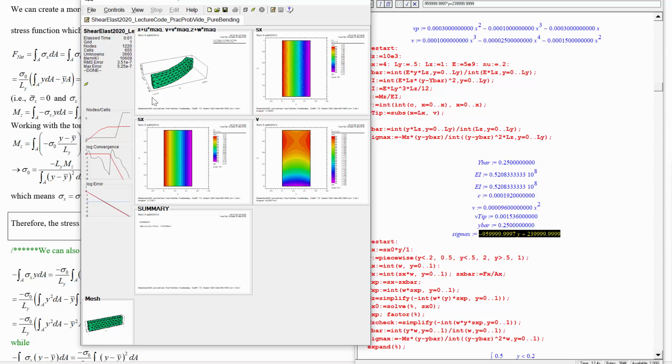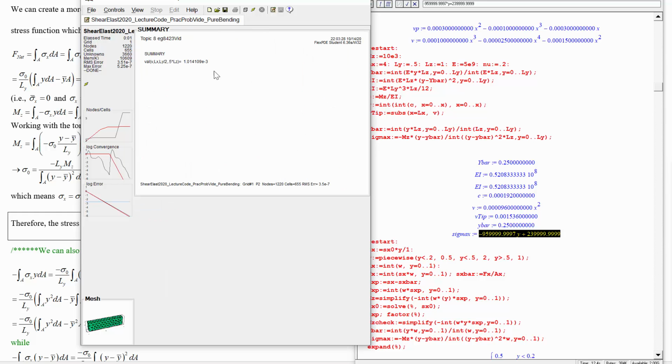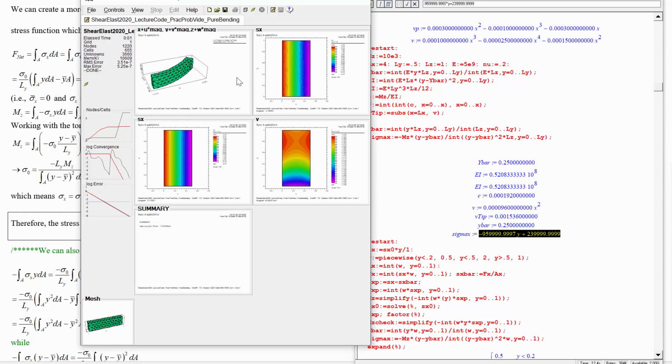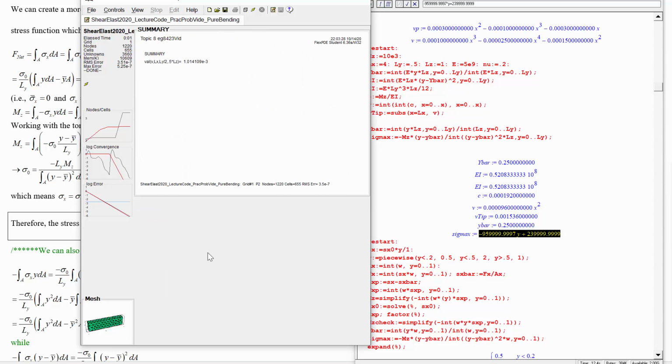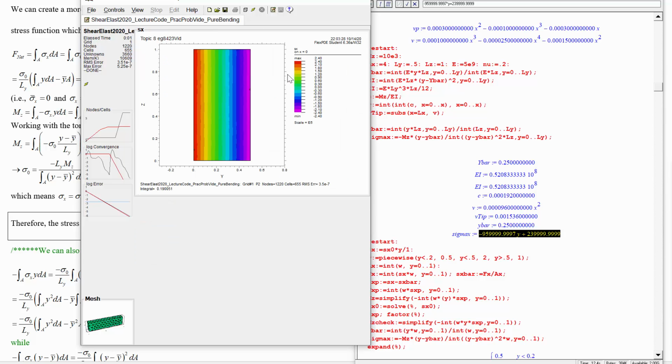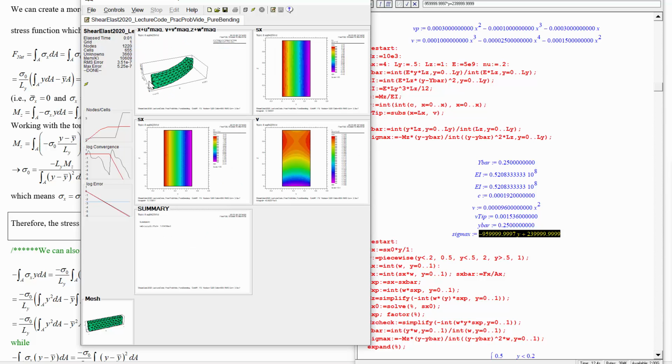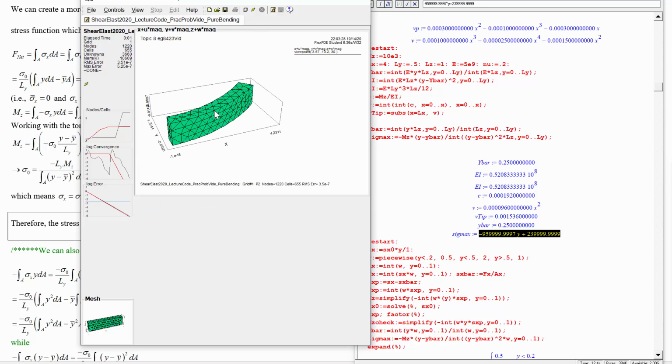However, the displacement is now kind of meaningless because we don't have a reference point where it's set to 0 displacement anymore. So although this is going to be a better way to calculate what the real stress is that's going to show up on that surface if we put it in pure bending, and now the beam is really in pure bending, we haven't held it still anywhere.